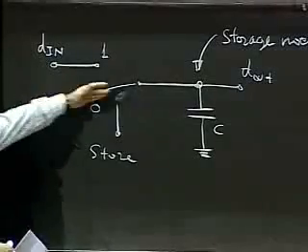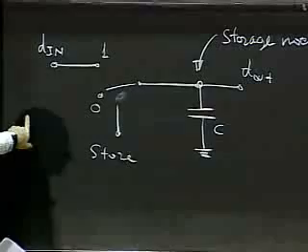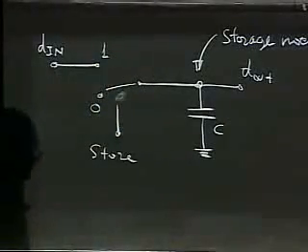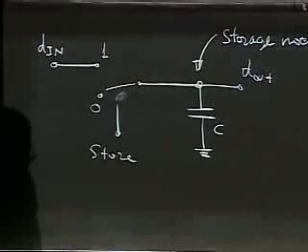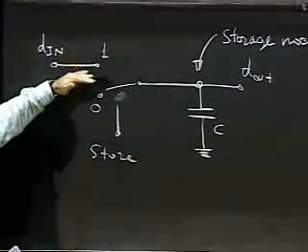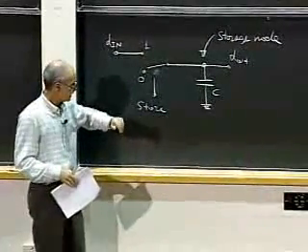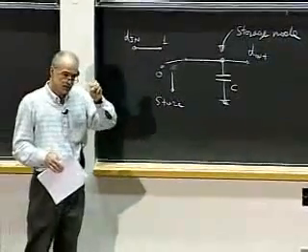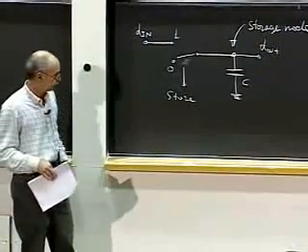If the input was, now the capacitor is at 5 volts. I put D in to ground. Okay? Flip the switch back up, then back down to its non-storing condition. What's the voltage on the capacitor? It's 0, exactly. Okay, so it does store the value of the voltage that it saw, 5 or 0, high and low, okay? It stores it because it stores charge, okay? So that's actually the physical quantity that is stored. It's manifested as a voltage, which we see, okay?